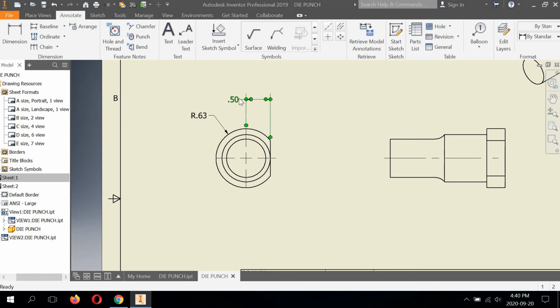You're going to notice that when you do these dimensions and you're pulling it up, there's a little broken line that appears every so often. This is basically giving you a reference of where you should drop these dimensions. Otherwise, how do you know where to drop them off? Like, one person might put it way up here, which is too far away. So you have to get into the habit of dropping it at a correct distance. So I would basically have it around here. Similar to the distance I've chosen for this radius dimension.